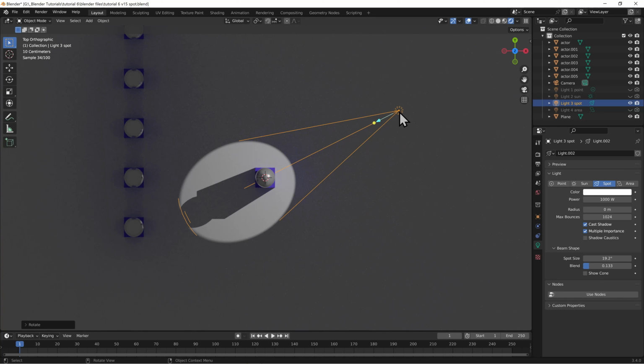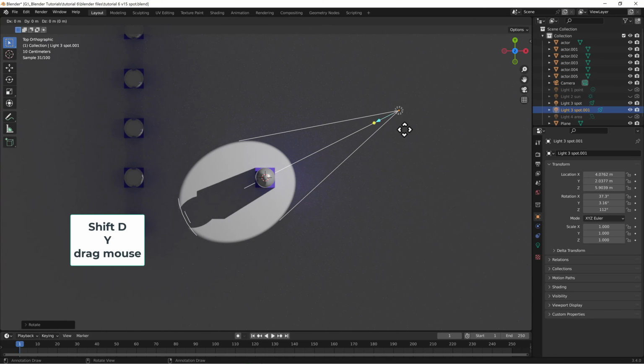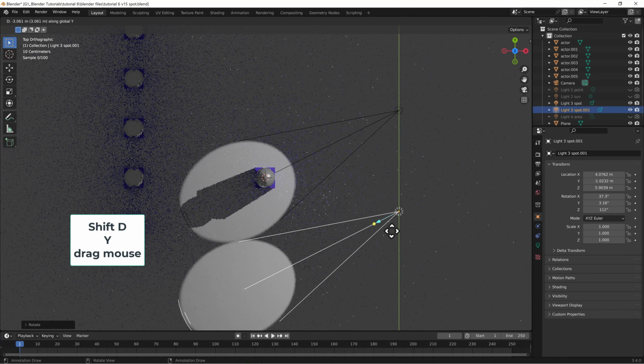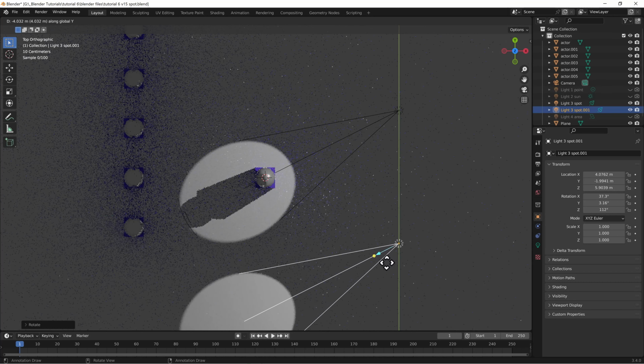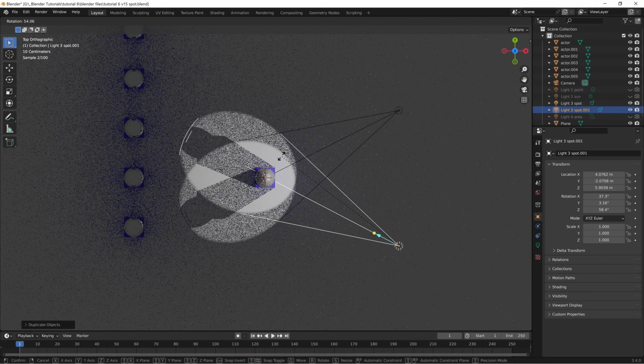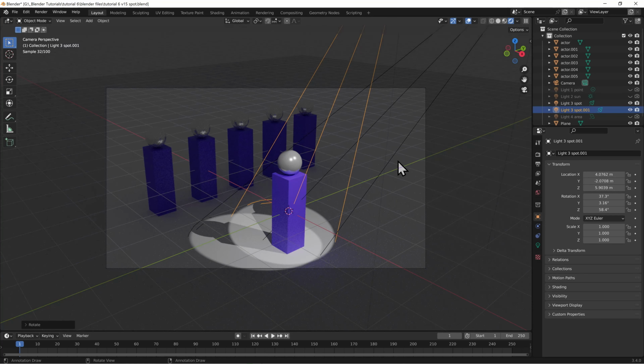Now I'm going to duplicate that light. So that's at around 2 in the Y. I want the duplicate to be -2. So Shift D, Y. I'm going to lower that until it's around -2. Done. Let me rotate that. Type R for rotate. Get that line going through the center. Go back to camera view. And there's my 2 lights for the rock concert.